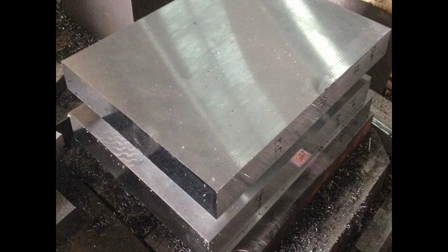Category 1. Materials like carbon steel, alloy steel, cast steel, and ductile iron can generally share the same tool. Currently, drills, milling tools, or turning tools mainly use carbide or ceramic tools. But taps are an exception. High-speed steel taps, also known as HSS taps, are still preferred.